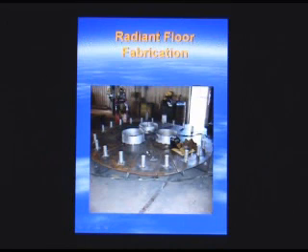This is the bottom floor plate. This unit had 3 burners. These are the burner ports. Castable refractory, or actually fire brick, will be put on the floor here. These tubes are the guide sleeves for the coils. So once the coils are installed inside the heater, they will penetrate through these sleeves, and it will hold the coil alignment.